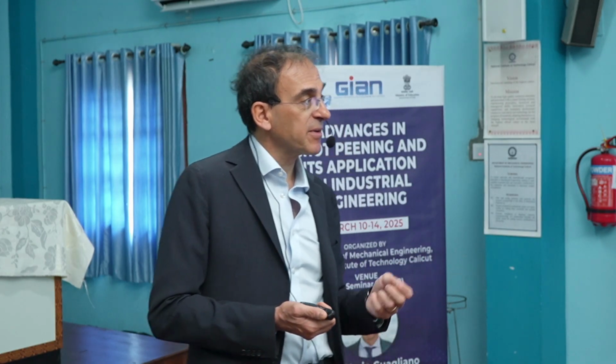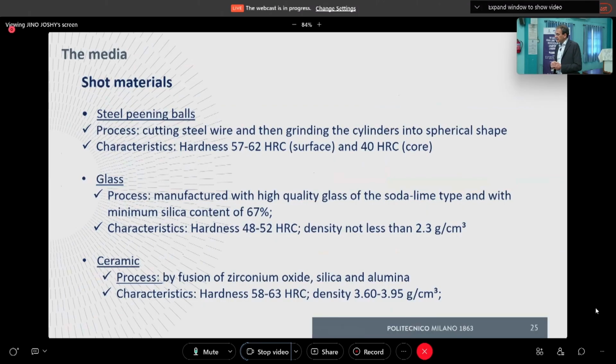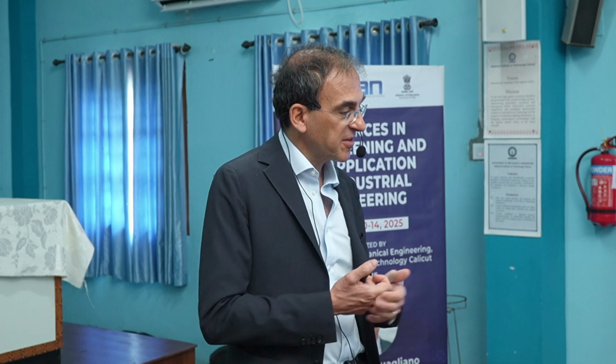For instance, if you are peening an aluminum part and we use steel, the surface will be contaminated. And if you don't want the contamination, because it's damaging the behavior of the aluminum anyway, we need to use some other material. Glass or ceramic are the most widely used.